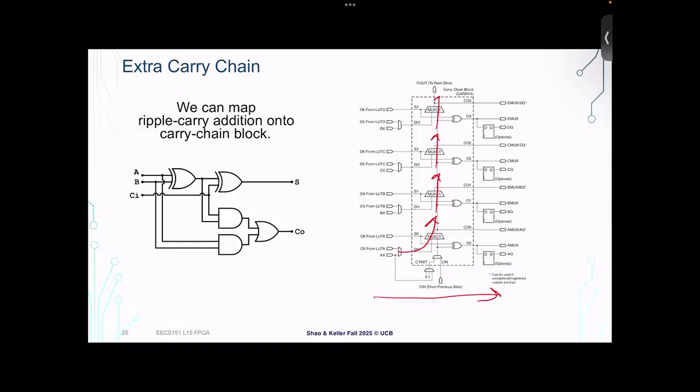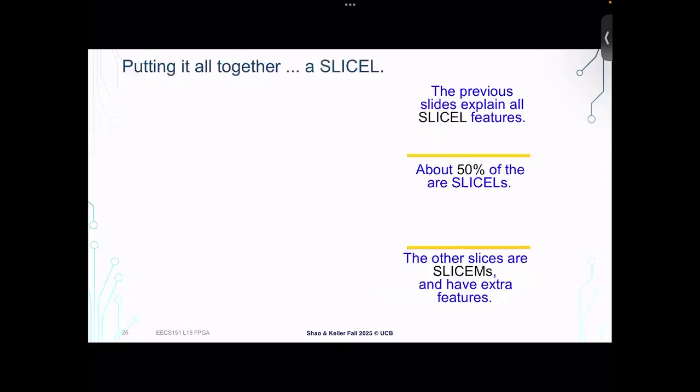Without the special carry chain, right? You just have to use extra routing stuff outside the block. Right, correct. You could do this with 4 slices, but a lot of the optimizations and why they've designed the FPGA this way is trying to be able to implement more and more logic blocks in fewer number of slices. Yeah, so you're absolutely right. This is an optimization. Okay, so oops.